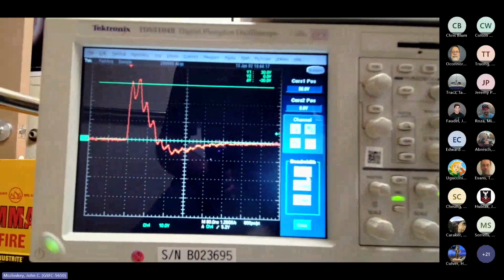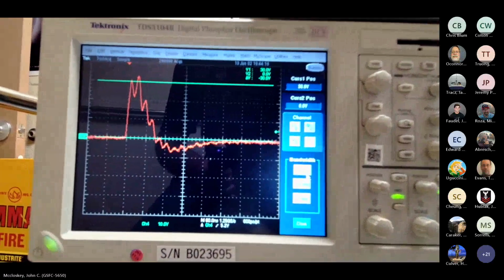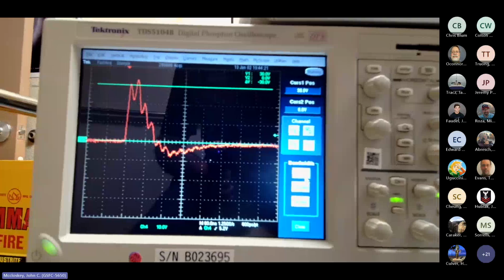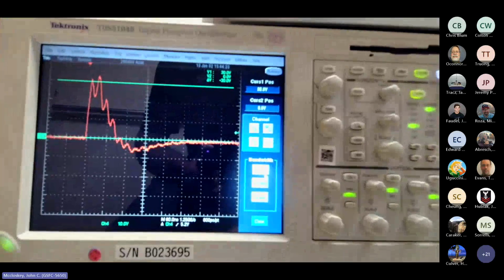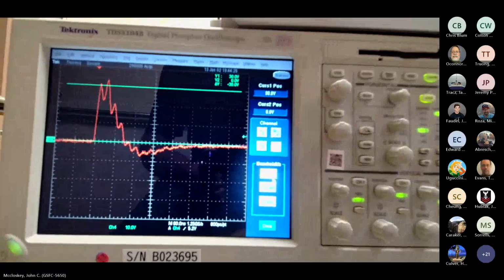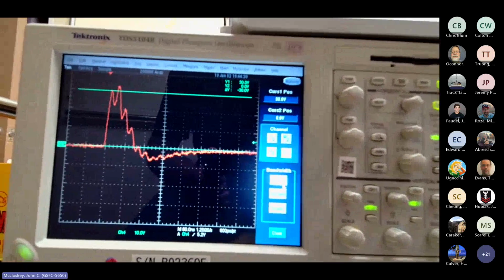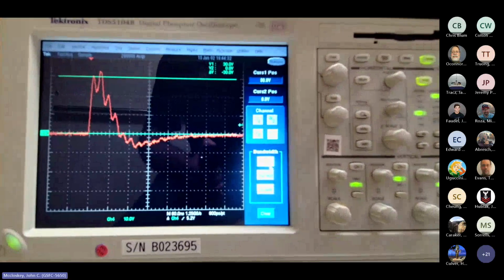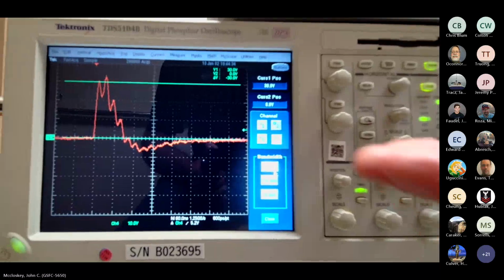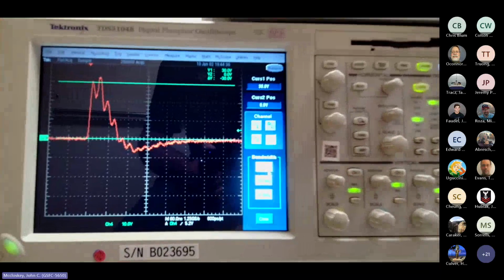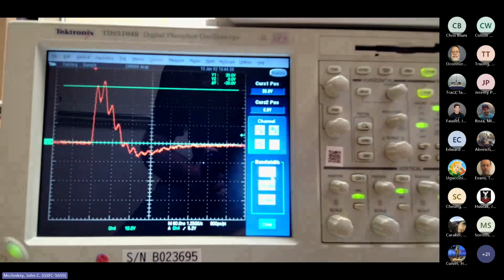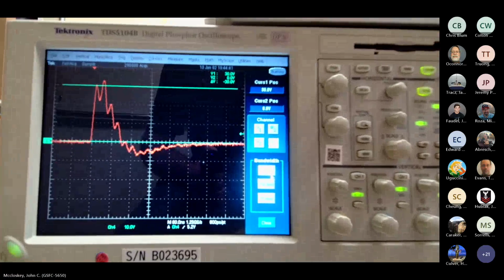You get what you get, right? So if it's way off, then the signal generator is faulty and you need to have it serviced. But I'm not going to be too concerned that I'm getting 130 nanoseconds instead of 150 or whatever it is. But here we are. That's the basic pulse shape you're getting for the 150 nanoseconds.